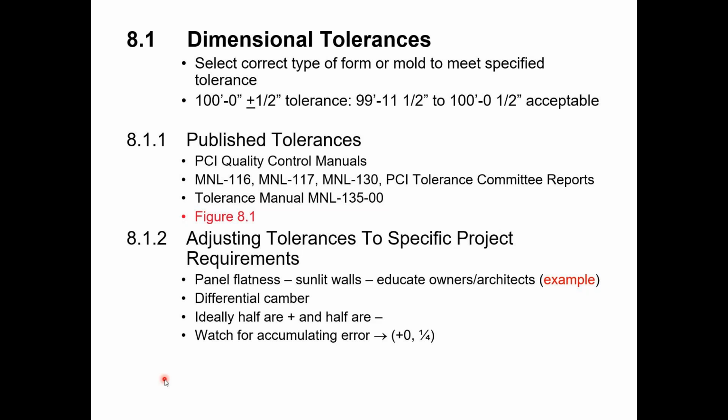That's not always realistic. There are going to be slight imperfections in the form that are very difficult to see with the naked eye under most lighting conditions. But when you see panels cast on a form with slight imperfections under a raking light, in other words sunlight shining on it from the side, you're going to see shadows start to appear that make the imperfections in the form very plain and obvious.